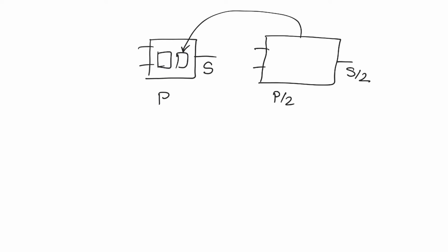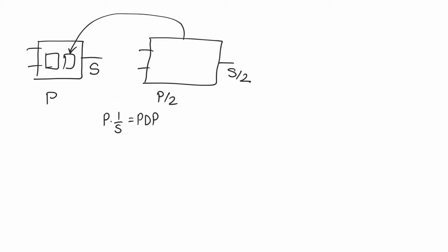And so when we talk about power, we should compare powers for the same throughput, or otherwise compare the product of power and the inverse of throughput, which is power delay product. So the inverse of throughput is the time it takes to produce a single output sample. When we multiply that by power, we get the amount of energy required to produce one output sample, and this is the best measure of power we have.